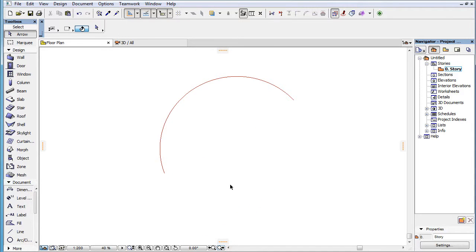When an arc or curved element edge is explicitly marked as a snap reference, the two endpoints of the edge are implicitly considered marked as snap references. This way, you can easily find the main axis directions from either of its endpoints, plus the tangent line, and the normal line to the marked curved edge at either of its endpoints.